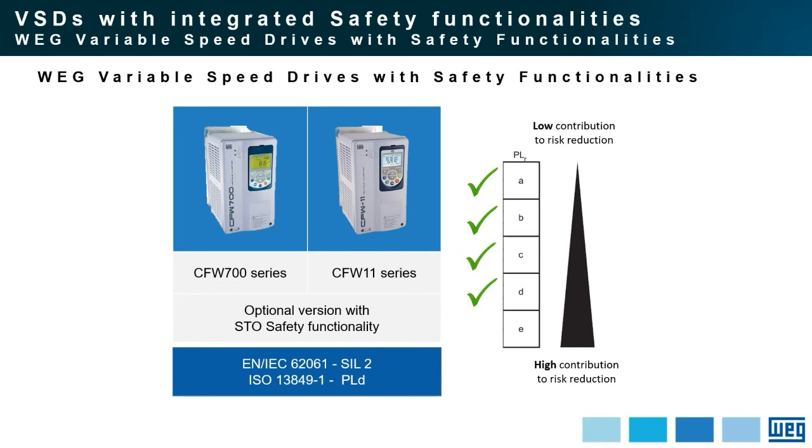Concerning IEC, it complies with Safety Integrity Level 2, and ISO standard, it complies with Performance Level D. So these two variable speed drives can be installed in several applications, from Performance Level A up to Performance Level D, without the additional safety devices we spoke about before.